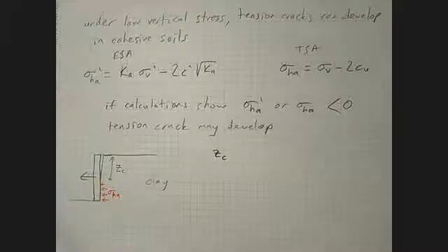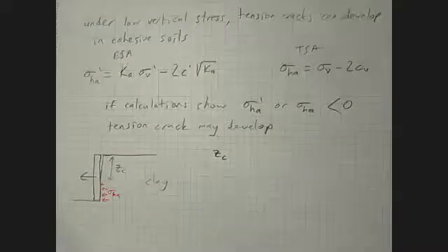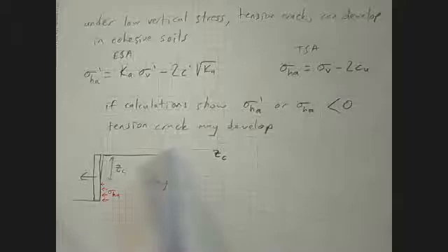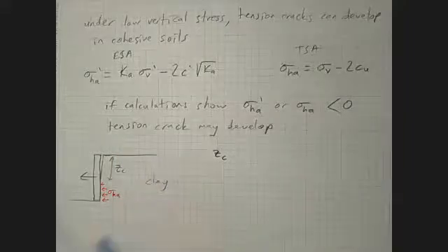You see a formula for that. Those will always take you to incorrect calculations. The reason is that they are always for very specific conditions, like no surface load, uniform soil, etc., and those conditions very rarely come together.